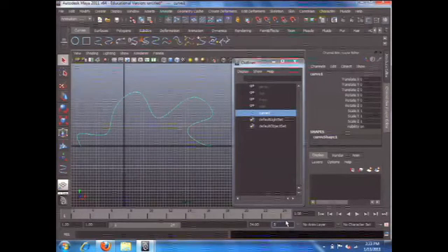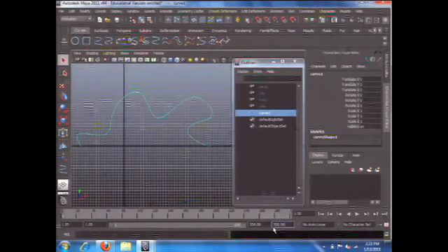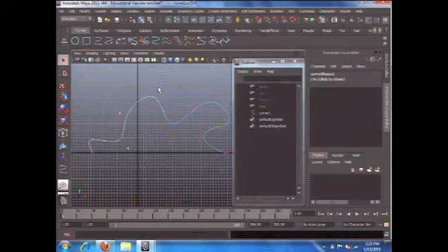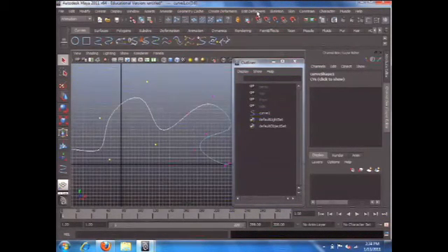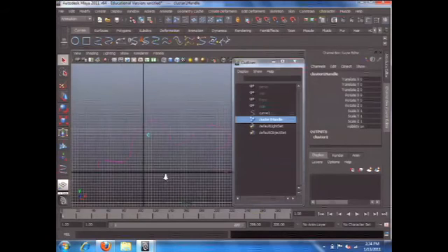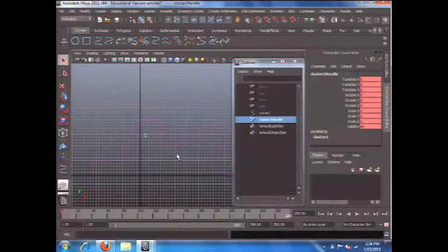Let's give 300 frames. And then I will choose some control points. Let's see, this point, this point, this point, this point. Okay, so 4 points are selected. Then I will create a cluster. In frame 1, I will use S keyframe. In frame 300, I will use R to scale and W to move. Right, I can use E to rotate and S to keyframe.